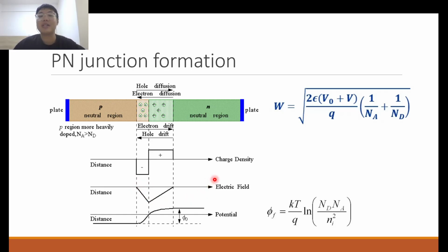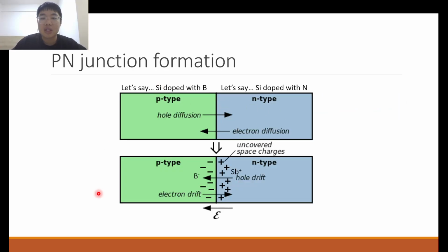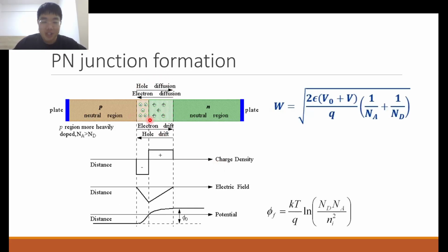Okay, so this represents the electric field in the depletion region over here. I forgot to mention this region is called the depletion region, right? Why? Because it's depleted of charge carriers. Charge carriers have all diffused away or drifted away, and what is left in the depletion layer are fixed charges. So these fixed charges create, as I mentioned earlier, an electric field that has this geometry within the depletion region. So there is basically a certain maximum electric field that can be computed.